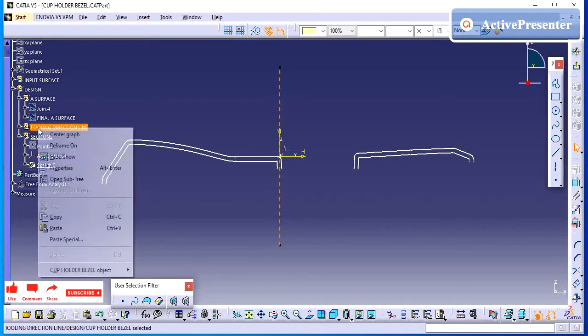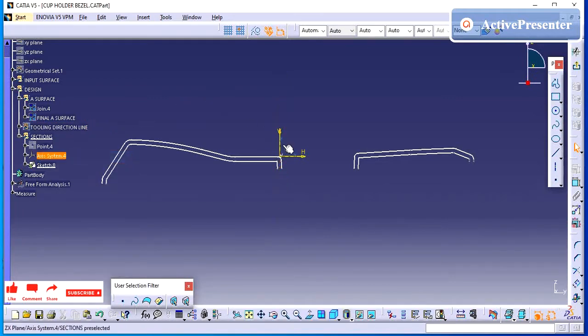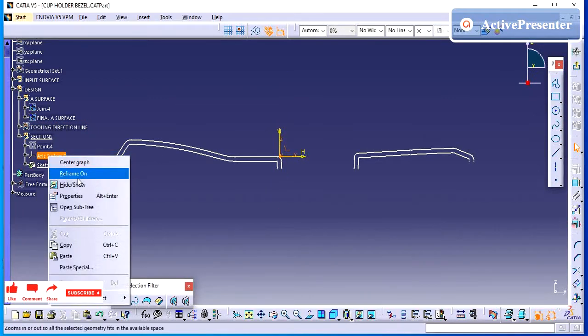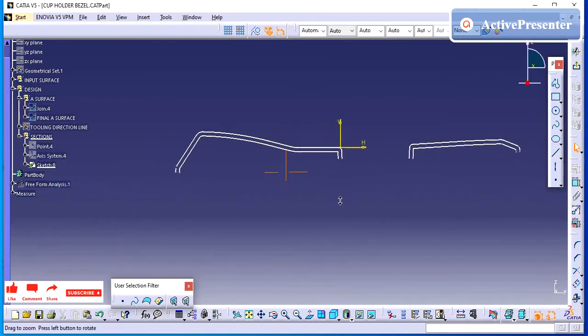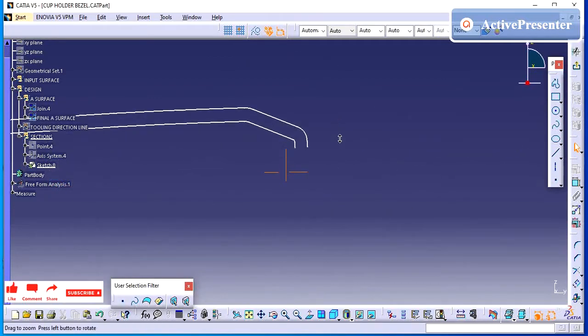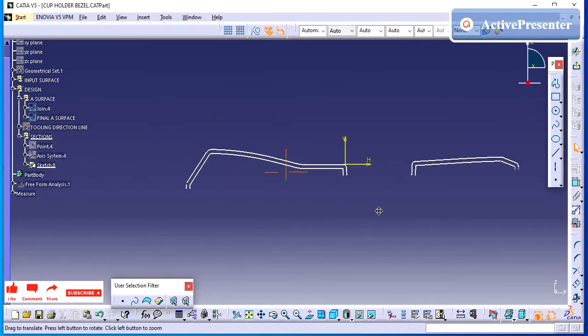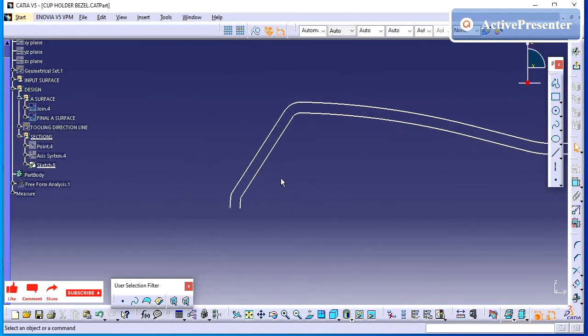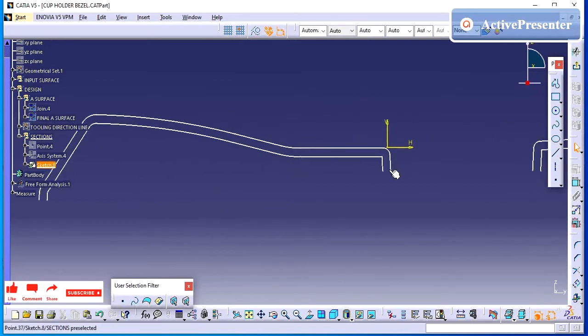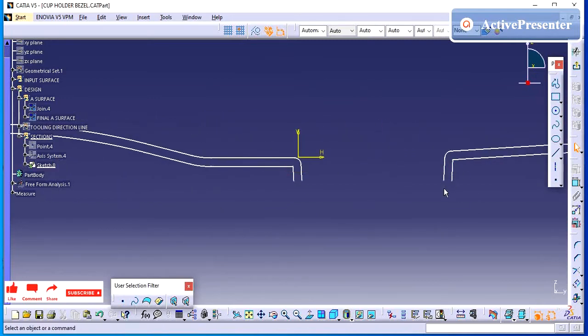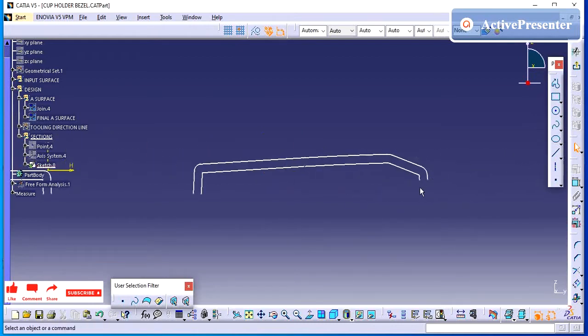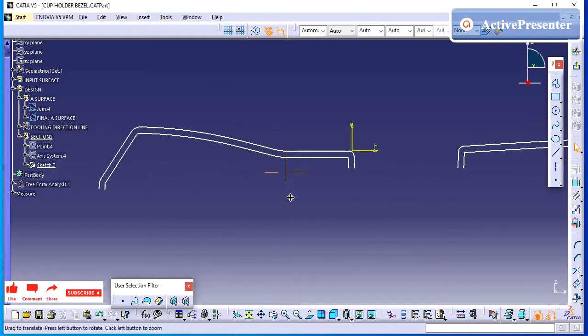I am just offsetting the same profile by 2.5 mm. Whenever you are creating the sketch, it should be on one axis and perpendicular to another axis. It should have two axes, then only will it be easy to understand the profile of the part. But for time constraints, I have created only one sketch at y0. The same way we need to follow for creating it on the plane of x also.